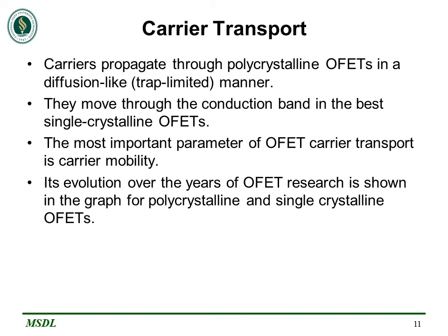Carriers propagate through polycrystalline OFETs in a diffusion-like manner. They move through a conduction band in the best single crystalline OFETs. The most important parameter of OFET carrier transport is carrier mobility.